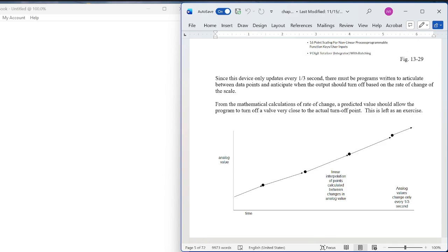So if you studied linear interpolation in a course and said, I'll never use this in the real world, think again, because this works very, very well. I've done this. Linearly interpolate. What you look for is when the weight changes, and when it jumps very much, you build a ramp of those weights. Then you can predict any place along this ramp in between the readings, because the feed accuracy is pretty accurate for the most part.